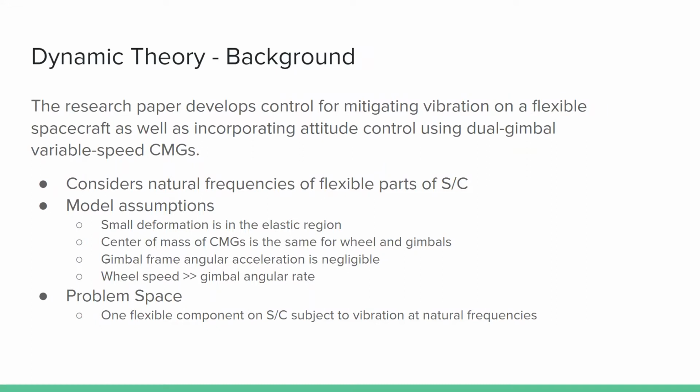Some of the model assumptions are small deformation in the elastic region. The center of mass is in the same position for the wheels and the gimbals. The gimbal frame acceleration is negligible, and the wheel speed is significantly greater than the gimbal angular rate.